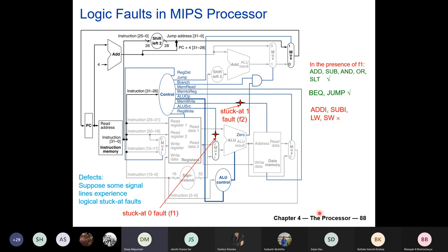But now it becomes like how we handle the don't cares, because if the write data path is not enabled, then it will not cause a problem. Correct. But if that is enabled due to a don't care, then that will cause a problem. Otherwise, some unwanted information might pass here, right? It is always enabled. So that means your safety valve is now not working. So in the presence of another defect, if the write data path is enabled, then somehow this wrong information may be stored in a memory location. So you see that in the presence of F2, these kinds of things might happen.